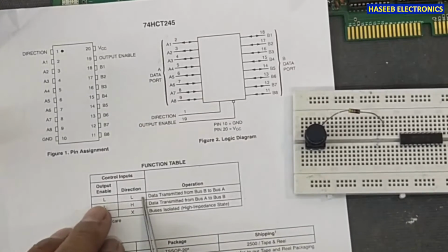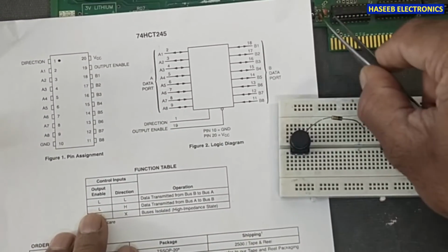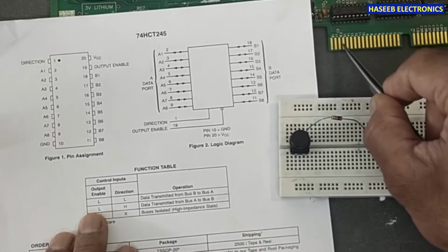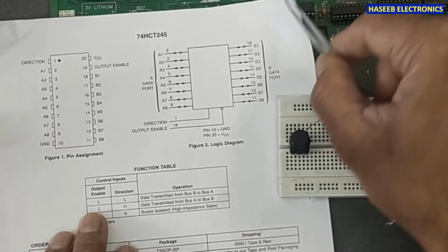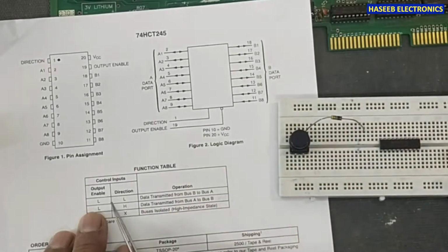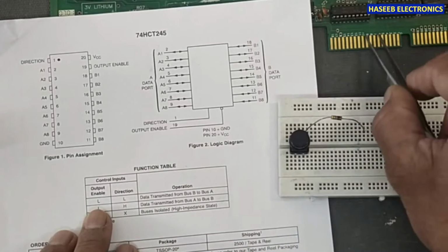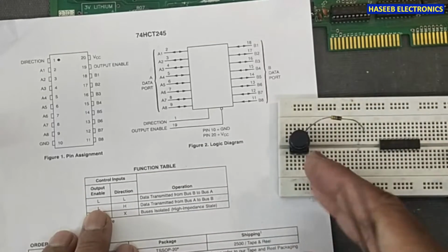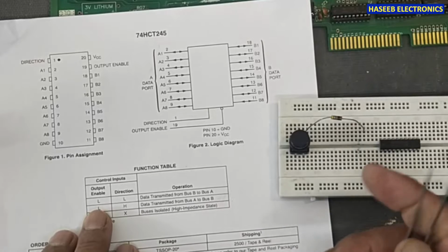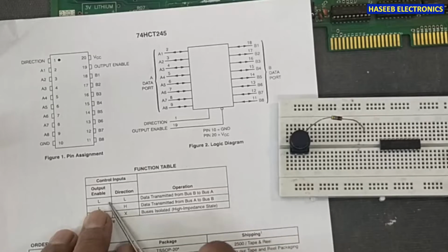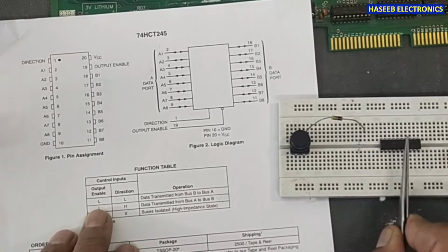Here is the combination of these two pins, which I discussed, where the address decoder LS138 uses this function. It receives 3-bit or 4-bit data from the microcontroller, from the computer, and it will decode and select the function of this IC.